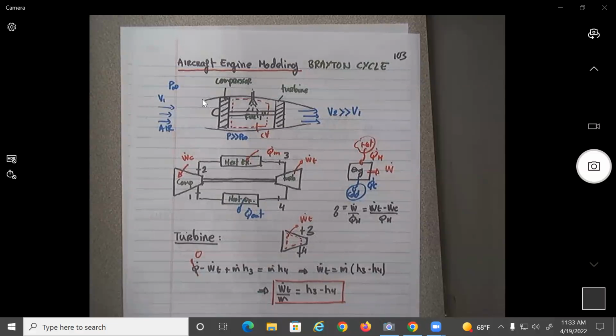Okay, so the cycle that is simulated is the one that you can see here below. The compressor simulates this one, then the turbine is simulated over here, and then we have two heat exchangers here, Q in, Q out. That's because any single engine or any single cycle in real life is going to operate between a hot reservoir and a cold reservoir. So you see here, this is Q hot, here will be Q in, and the Q cold over here will be Q out. You see the colors match.